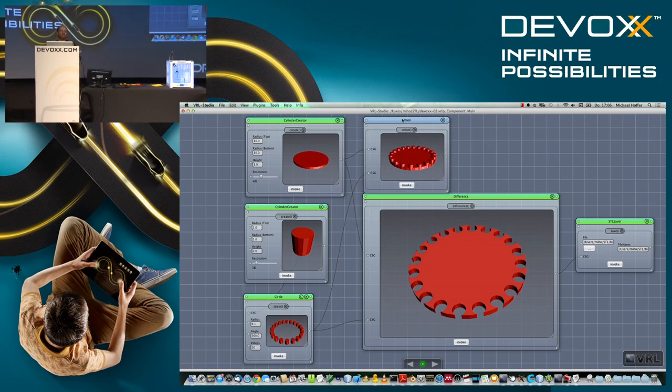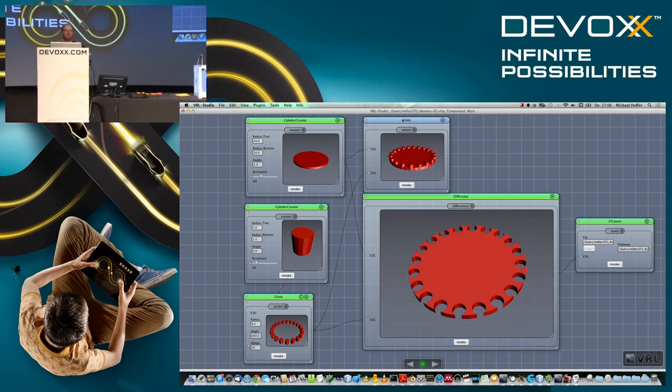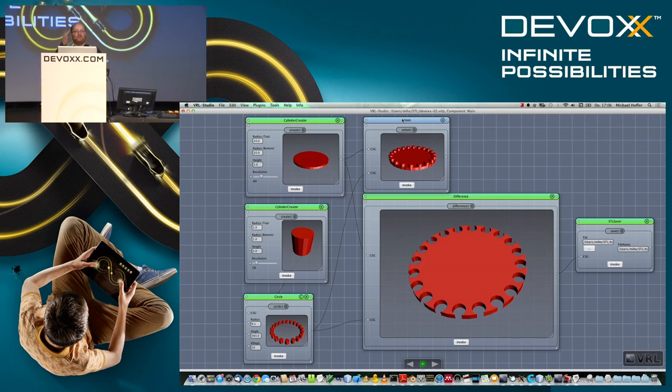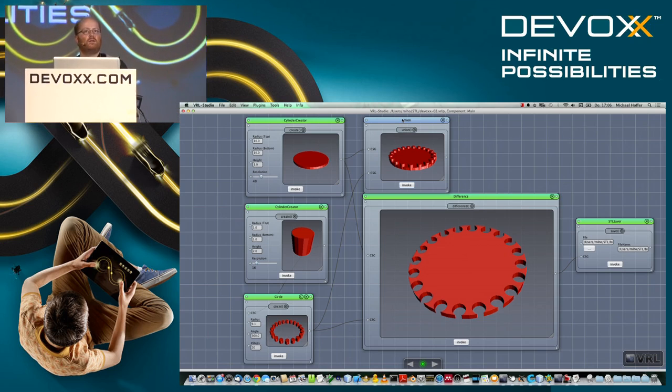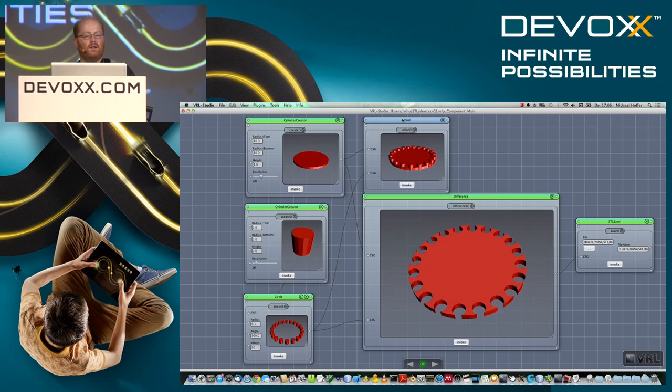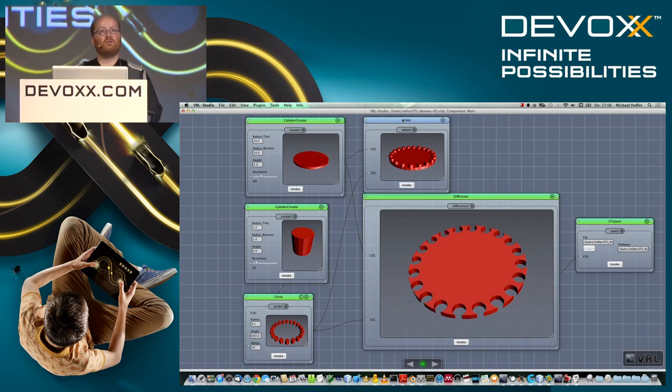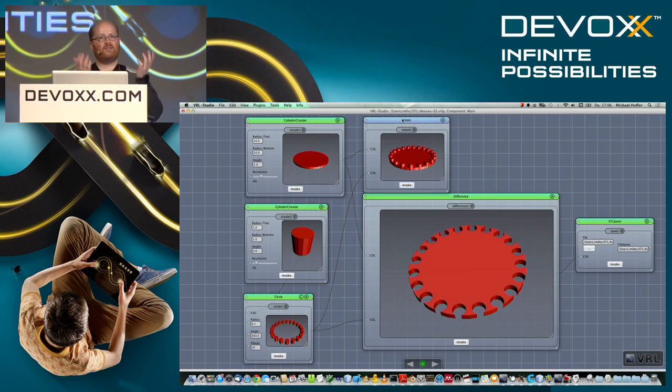So, do you have any questions about the visual programming environment? Is there anything you... Yeah? The cube you just showed, is that a solid cube or just layers of 0 pixels? So actually it's just polygons. So it's not filled, but the printing software will fill it. So it just has to be a closed surface, and it will assume a solid object, actually.